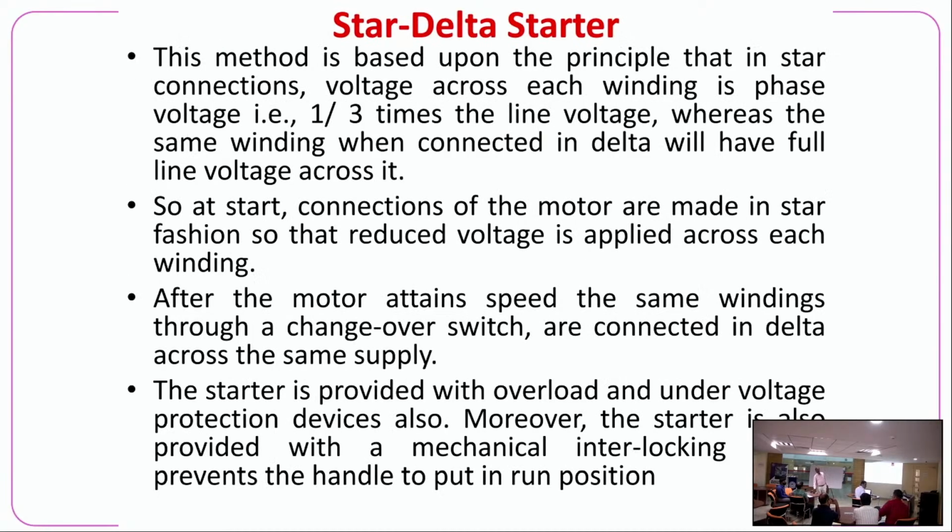Then another starter is the star delta starter. Star delta starter means we start with star and then change to delta. Most of the induction motors are delta connected. Some are star connected, not all, but maximum induction motors are delta connected, particularly bigger motors. To reduce the starting current, they are connected in star at the time of starting.